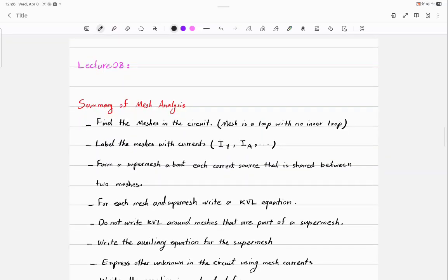Yes. And then all parallel elements. Yes, exactly. Everything that comes in parallel with the voltage source goes inside the supernode, which means they don't contribute to your KCL equations. And you remember why. Because one appears with positive sign in one equation, one appears with negative sign in the next equation, and if you add those equations together, they cancel. Okay? This is how I actually proved that for the first time in class.